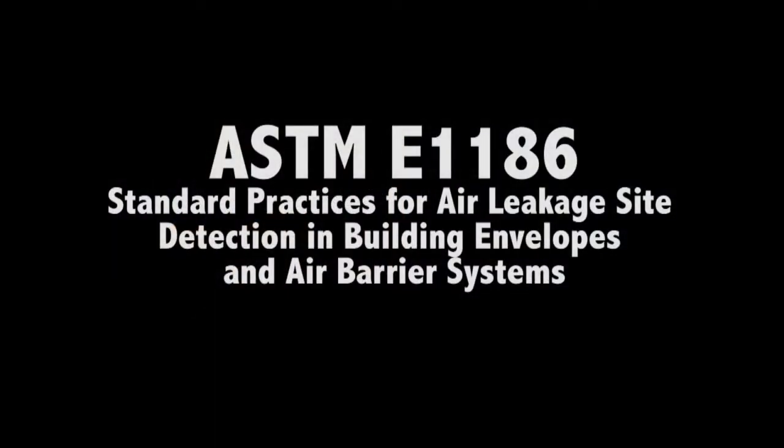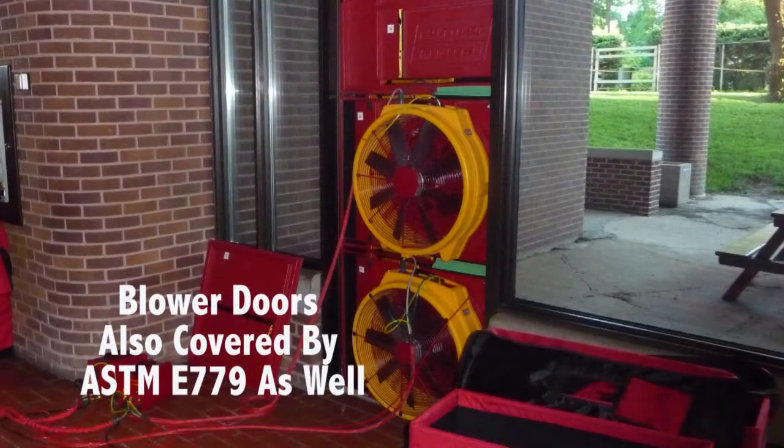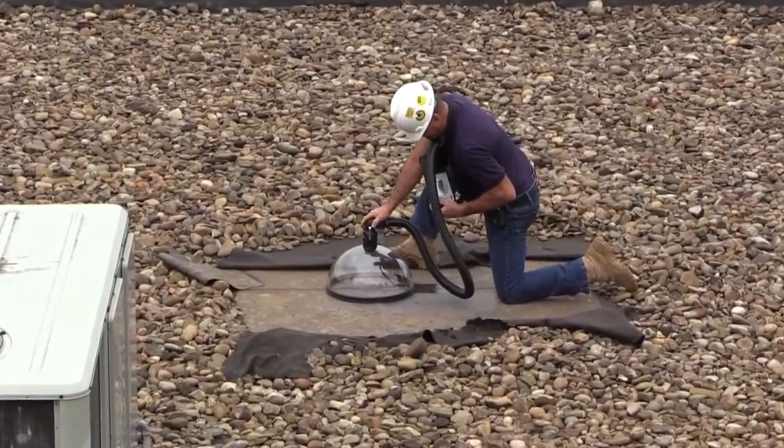ASTM E1186 is the industry standard for air testing. Five methods are performed upon completion of construction. Two other methods are for localized testing of ties, for example. Again, the chamber is being placed over the tie, a pressure differential is created, and the leak is shown by virtue of the bubbling. The Positest is described in 4.2.7 of the standard, and it can also be used for forensics work, for example, on this roof after the fact, looking for leaks.